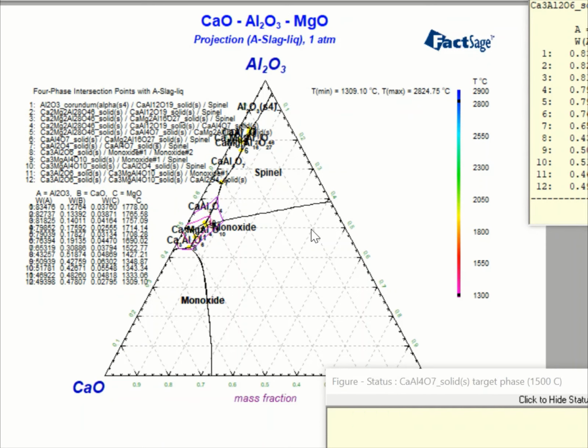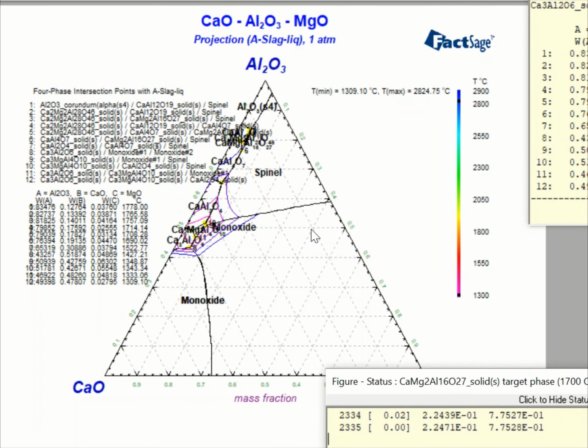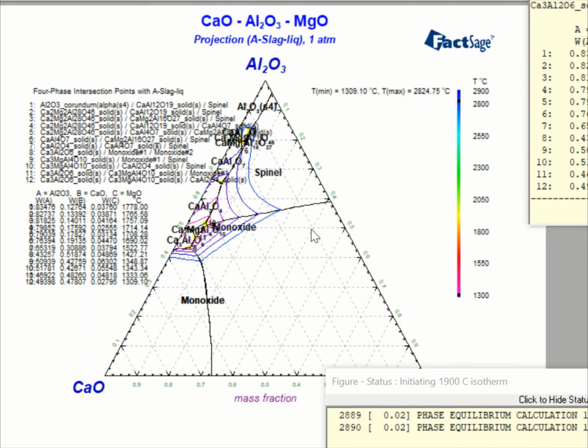And you can do this kind of liquidus projection not only for a ternary system, you can do it for a multi-component system. So as we did before, you have 3 components plus a 4th component, you can pick the constant value, and then you can do this kind of calculation. Then it will give all the liquidus projection in the quaternary system as well.